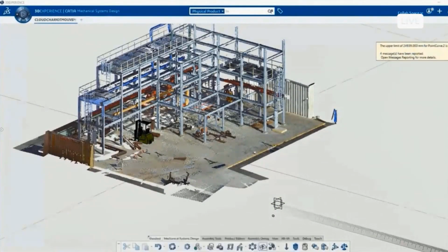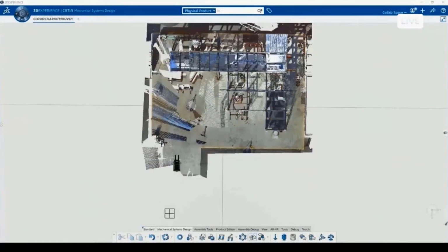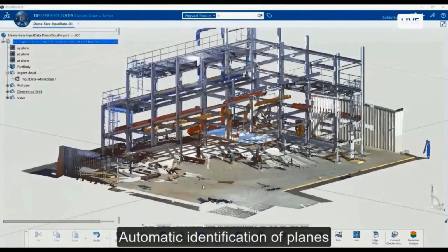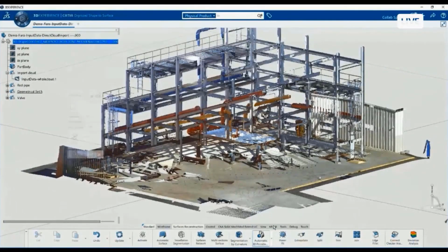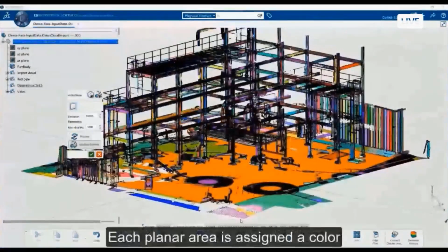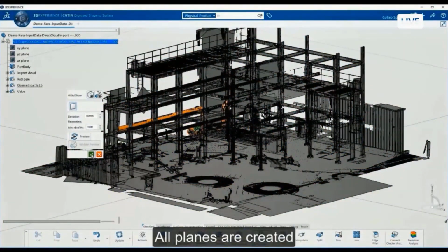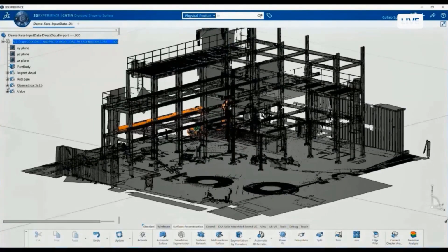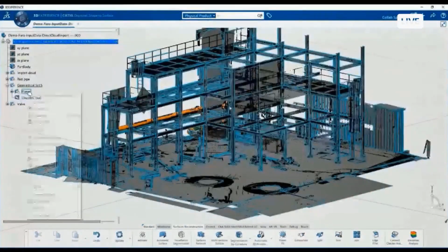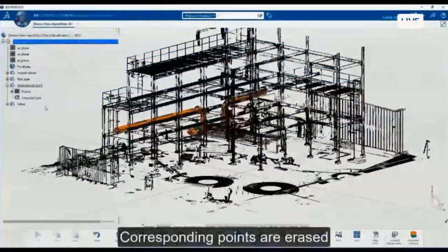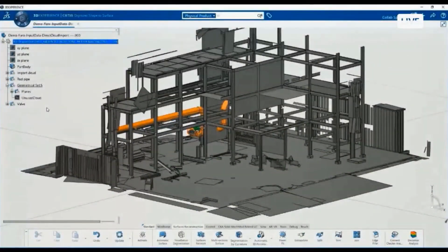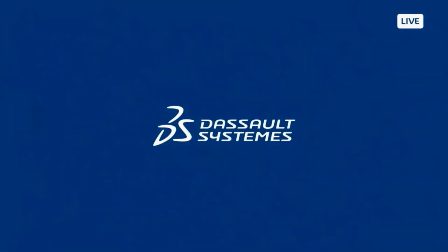Another scenario is a maintenance scenario in order to check feasibility of mounting and dismounting equipment like you see here. And the latest tool that we are providing is the possibility to generate automatically all the planes. For example, here on the 73 million points, we automatically detect all the planes, segment them by color to a given accuracy. And here you see the result of the generation of planes inside your model. And more to come in the near future. You will get automatic recognition of cylinders to complete the pipes, not manually anymore, but automatically this way.